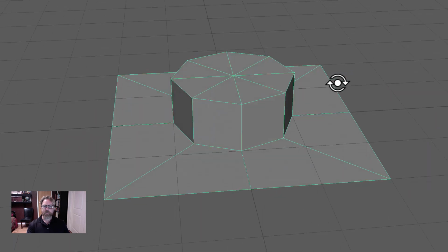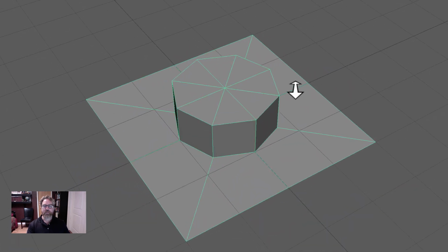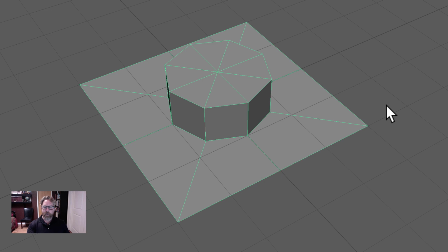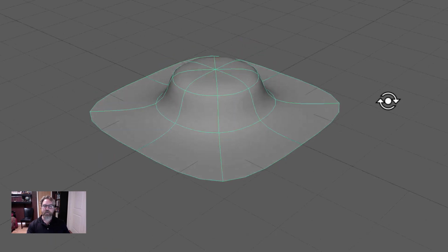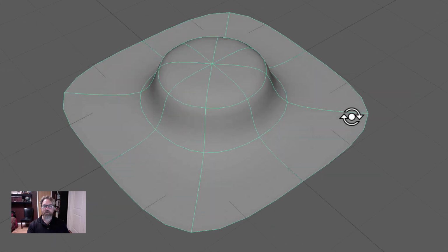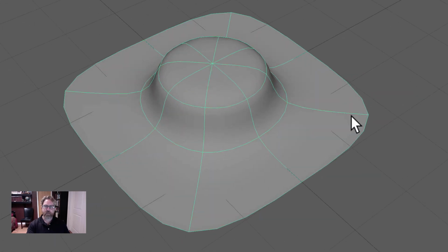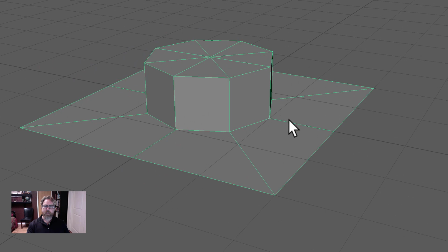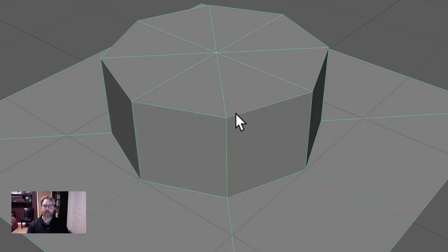And a word here on subdividing. We are ultimately going to subdivide these bricks. Remember that the 3 key is a shortcut to show us what a subdivision will look like, one subdivision. I'm going to hit that back to 1. And so we don't want it soft, so we want to add edges around here, and we can do that with the bevel tool. Rather than manually adding edges, the bevel tool will automatically create edge loops parallel to the edge that we have selected.